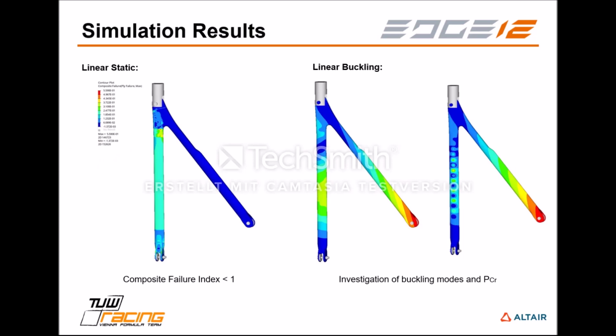Looking at our results of the linear static load case, in this case the composite failure index, which is for the whole structure below 1, which is good and tells us that our laminate is not likely to fail. We used the Tsai-Wu failure theory, which can be chosen in the PCOMP property card, and looking at the linear buckling analysis, you get your different buckling modes at your different loads, and you need to investigate what buckling modes and, in further case, what critical loads you need to consider in your application.